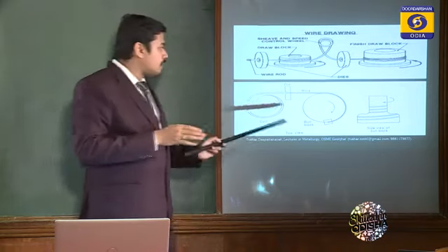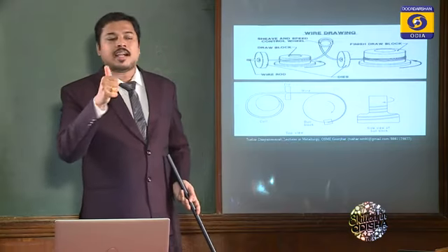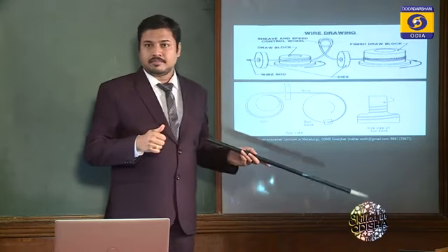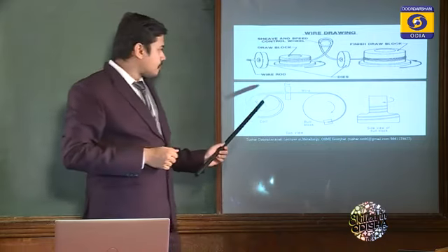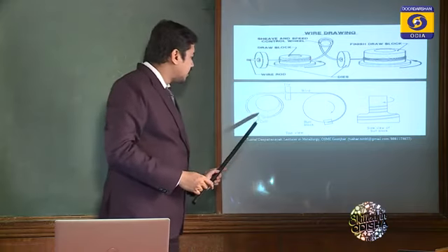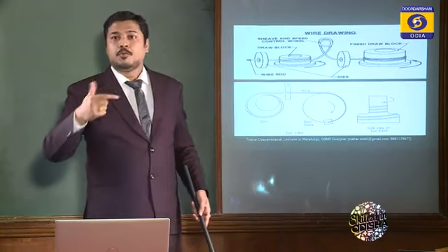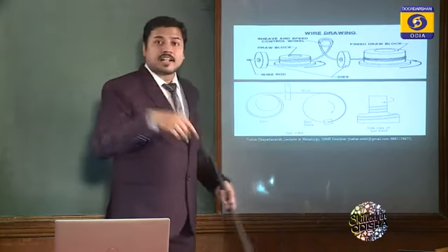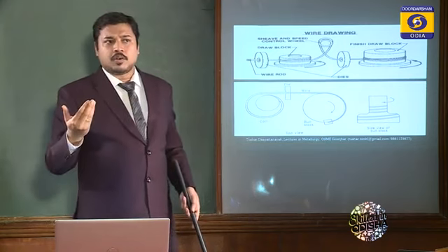In this way, if I use 5 different systems, I can convert smoothly defect-free wire out of 6 mm rod. Do you get me? For that, if I use 5 different systems, I need greater space, more space. 5 different drives is required, 5 different motor is required. Energy consumption will be more.